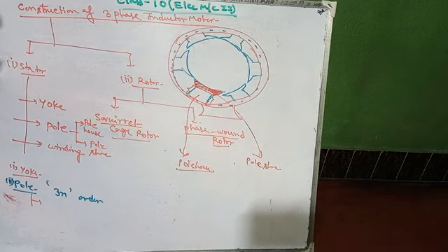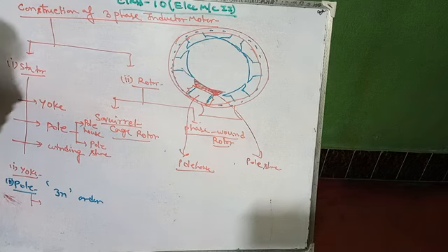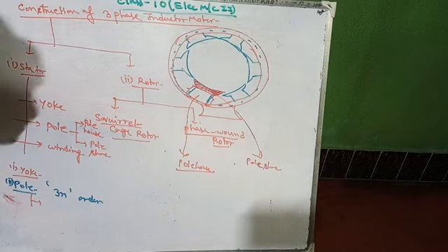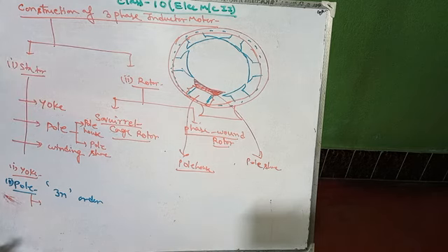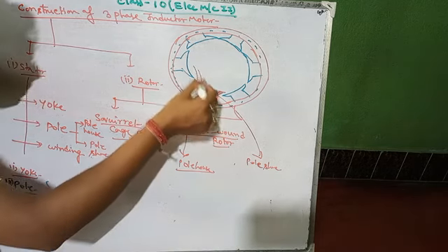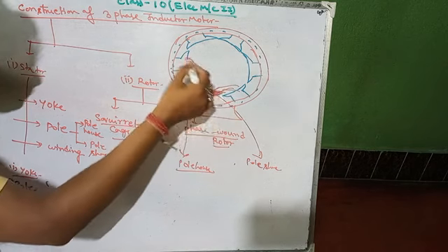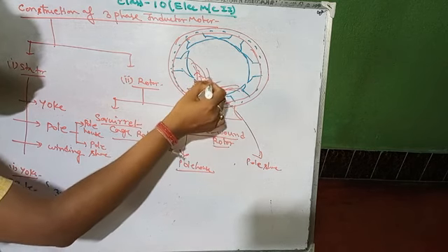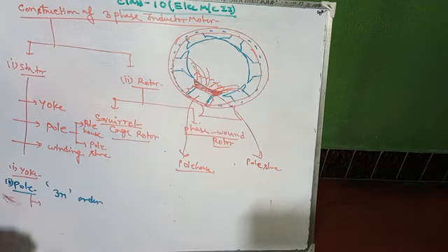Pole house holds the windings, while pole shoes are used to distribute the flux generated by the windings. Whatever flux is generated, the pole shoe distributes throughout the air gap.